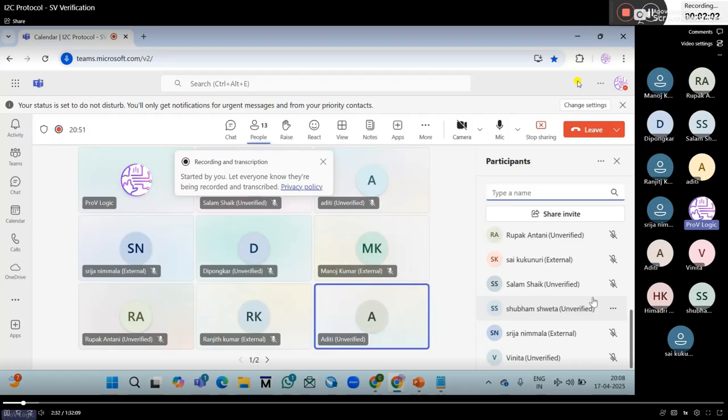Okay, how can we write clock stretching in design code? Coding wise, how can we write the clock stretching? Using an if-else condition. When the clock stretch is high, we select the clock line to 0, and if it's low, then we select the serial clock line.